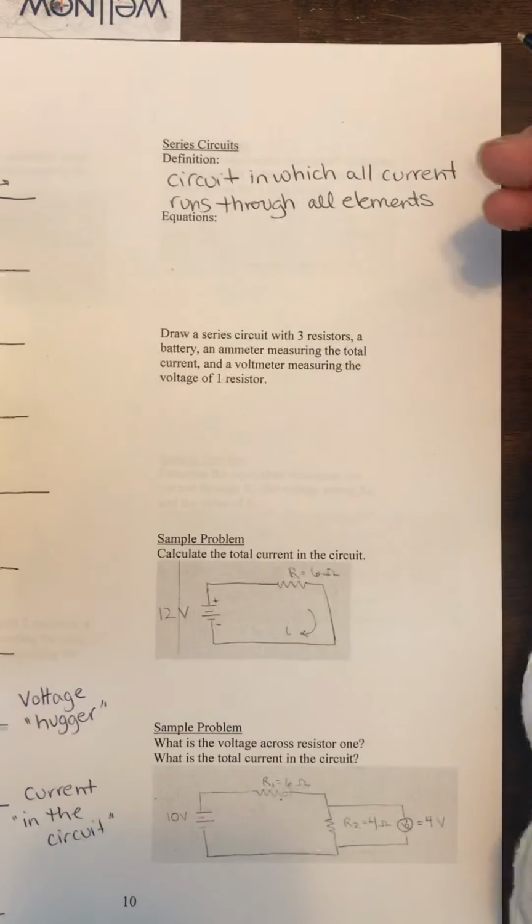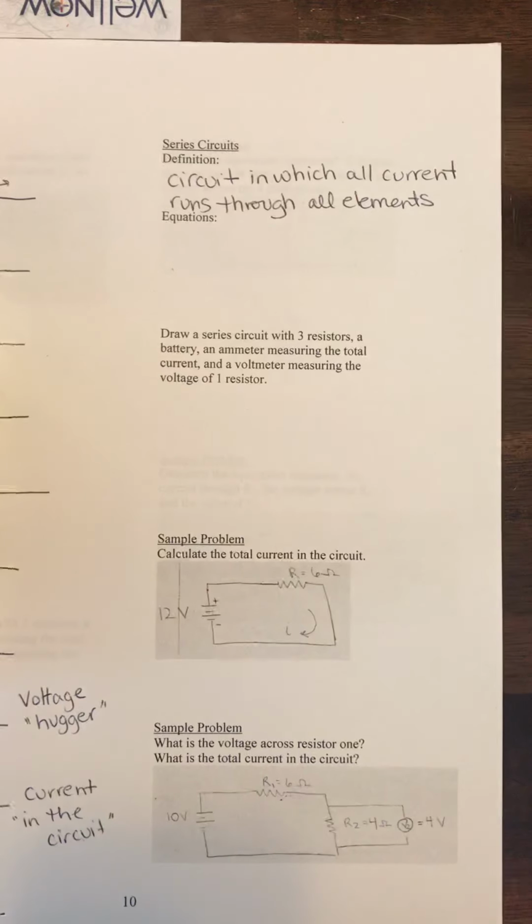Now, have you ever watched the movie Christmas Vacation, where he puts all the million lights on the house and then he goes to plug it in and it doesn't work? The reason why that happens is because they used to make Christmas lights in series circuit. So if one bulb went out, the whole thing wouldn't work, okay? Because the current runs through all the elements, so if one element is broken or bad, then none of them are going to work. But they've since changed it, and they've made them a parallel circuit, which allows them to work in case one light doesn't light, okay?